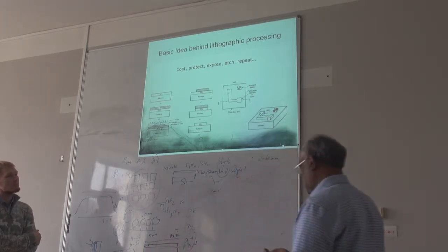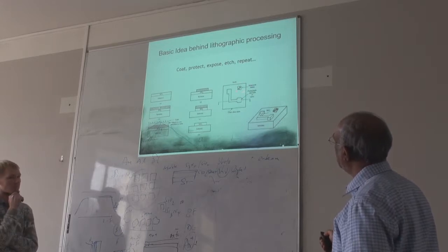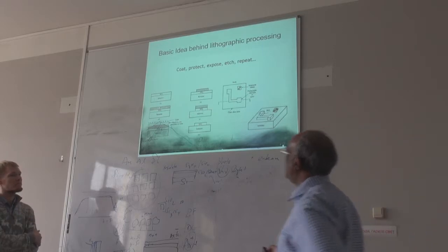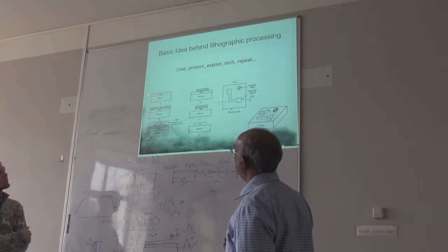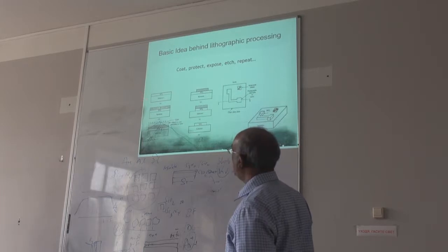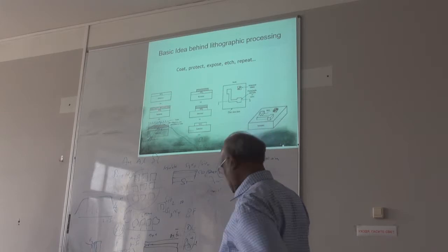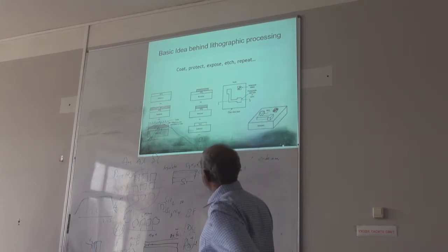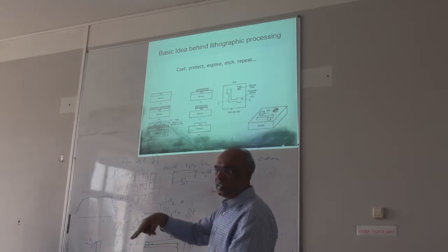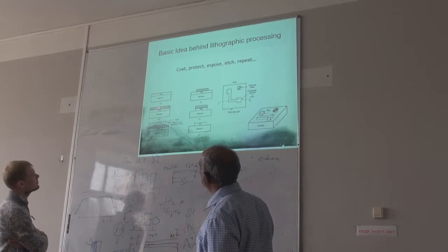So in the mask, you need to have, so this is the mask, and this is that alignment mark here. Then what do you do? You take your silicon substrate, you grow your silicon dioxide, that we already did, right? Then we have something called photoresist. So on silicon dioxide, how do you do this? You can do the spin coating. By spin coating, you can apply your photoresist.